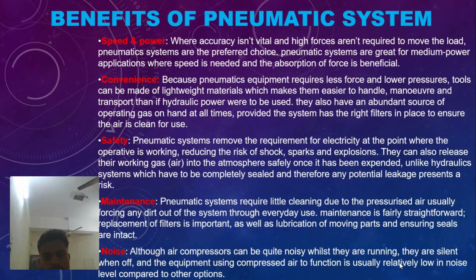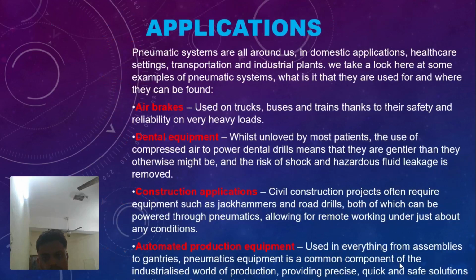Maintenance. Pneumatic systems require little cleaning due to the pressurized air usually forcing any dirt out of the system through everyday use. Maintenance is fairly straightforward. Replacement of filters is important, as well as lubrication of moving parts and ensuring seals are intact. Noise. Although air compressors can be quite noisy whilst they are running, they are silent when off, and the equipment that uses compressed air to function is usually relatively low in noise level compared to other options.